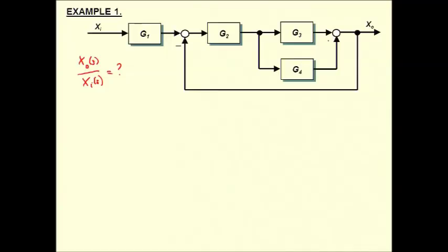So we need a bit of block algebra to actually simplify this. I mean, we could write all the equations down that this represents, a first principles approach, but you'd have a ton of equations and you'd probably make mistakes. It's far easier to simplify the diagram first and then only use equations when you need to. That's my general advice. So how do we simplify this? Well, you first look for inner loops or objects that you can simplify first before you go into the outer ones. So I notice that between here and here, this stuff is all alone.